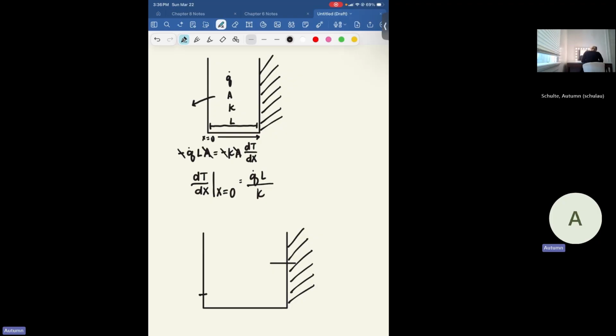From the other side, the uninsulated side, our temperature profile is going to look something like this. Just like I had said previously, it is a parabola. Even though we don't have both sides of the parabola, it is still a parabola. And the reason our slope is increasing is because if you just take a look at the right side of our temperature profile, we can see that we only have half as much heat being generated. Therefore, only half as much has to leave, so our slope is not going to be high. Whereas if we look at the total picture, all of the heat is being generated and all of it has to leave via conduction. Therefore, our slope has to be greater.